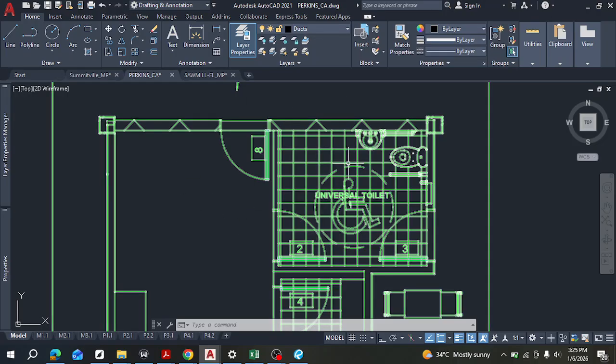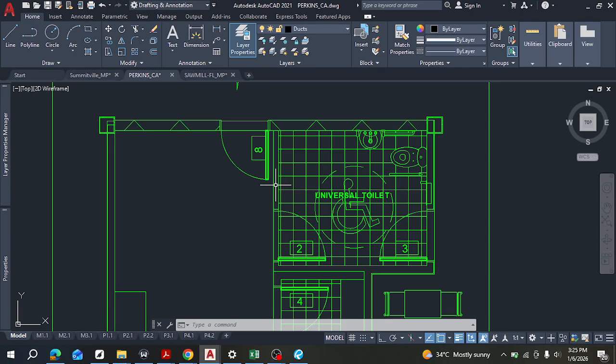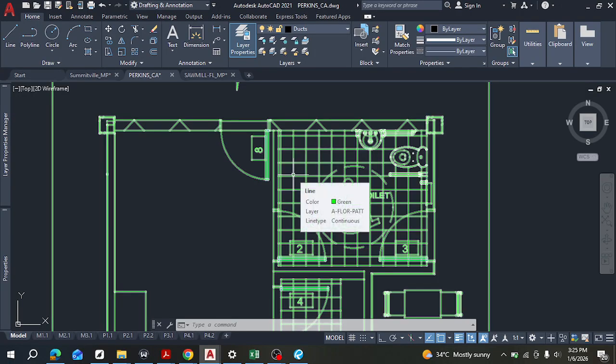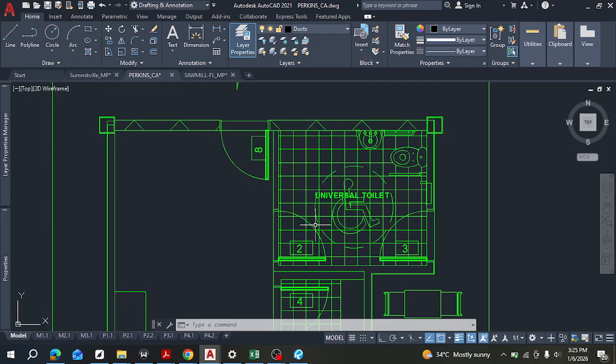If ever you stumble across a case like this, there's this particular thing called a mop sink. For commercial buildings, the bigger it is, the higher the demand for mop sinks. A mop sink is a type of sink that is used to wash mops, for very dirty applications where you cannot rinse and wash in the kitchen sink, right? And it's usually a standard compulsory item for commercial buildings, right?